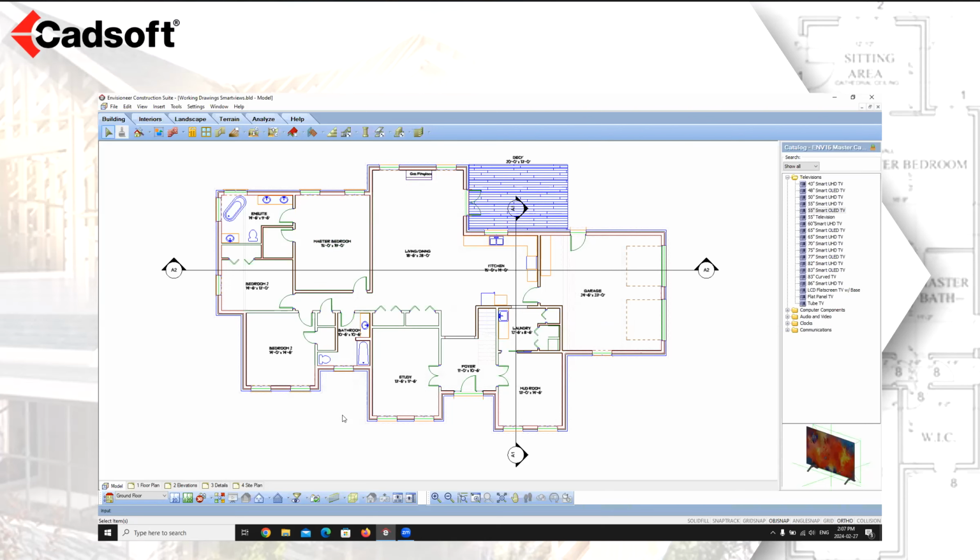And so now we're just going to talk about inserting scaled views onto a worksheet. So when you're inserting views into a worksheet view, you need to determine an appropriate scale for each view. At full scale, a floor plan would not fit on a piece of paper. So the drawing is always going to be scaled down in size. The scale, again, is going to be the ratio of the units on paper to units in the real world. And again, we use the 1/4 inch scale as our default.